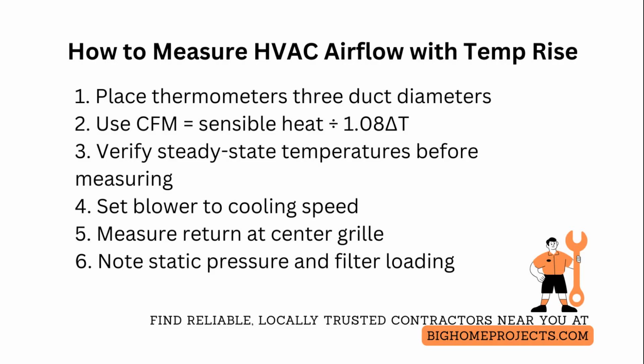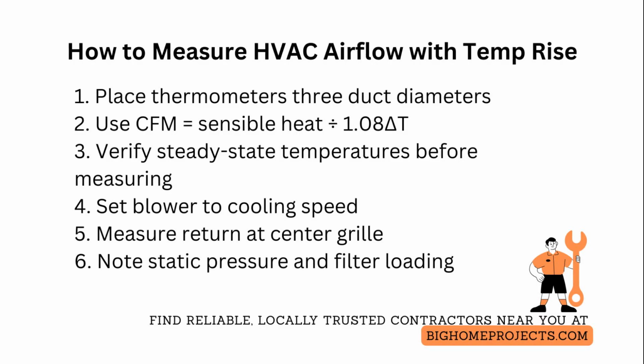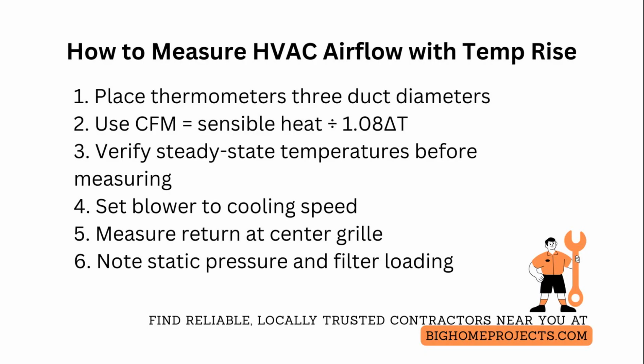When testing cooling, switch the blower to the higher cooling speed before measuring, measure supply and return wet bulb temperatures if possible to account for latent load, and use sensible heat only when calculating airflow for heating tests.